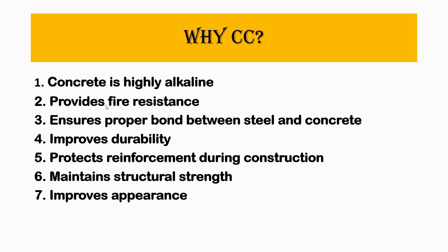We all know that concrete acts as an insulating layer during a fire. So that cover block provides that fire resistance. The third point is that concrete covers ensure that there's a proper bond between the steel and the concrete. Adequate cover helps develop sufficient bond between the concrete and the reinforcement. If there is no cover, there will be less bond between the concrete and the reinforcement. It improves durability, protects the reinforcement and also maintains structural strength. It improves appearance as well. So these are a few reasons that we need concrete covers.